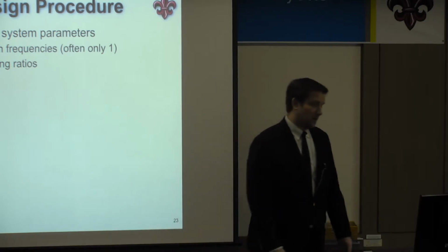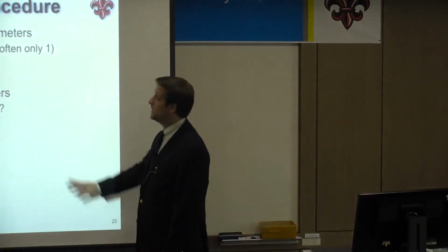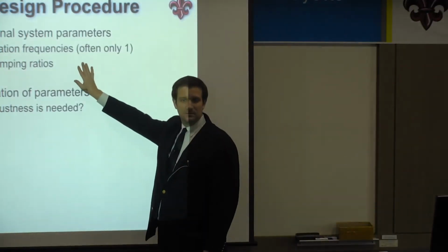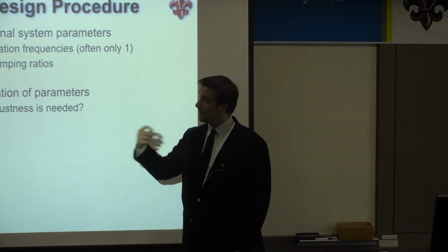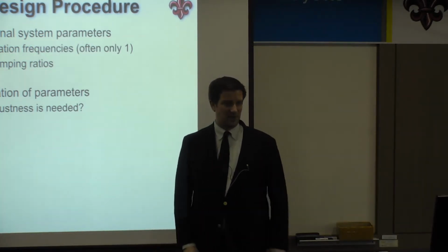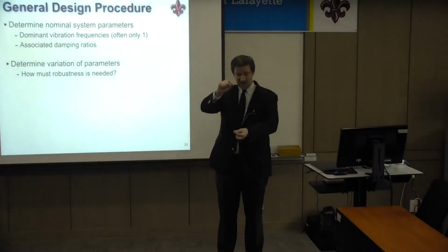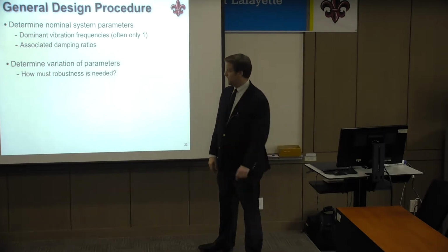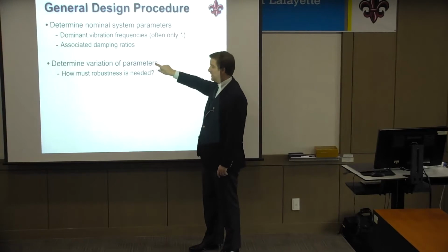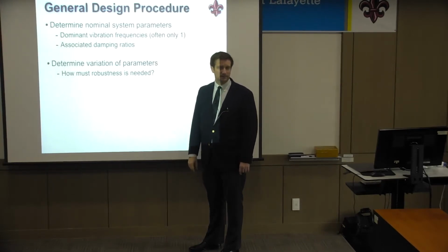Then you need to determine how much variation there is in these parameters. How much error is there in my estimate of those natural frequencies and damping ratios? Or how much is my frequency changing while my system is operating? So for example, the crane: as L changes, as I start hoisting up or hoisting down, the natural frequency changes. So I need to figure out how much it changes so that I know how much insensitivity I need to changes in natural frequency.